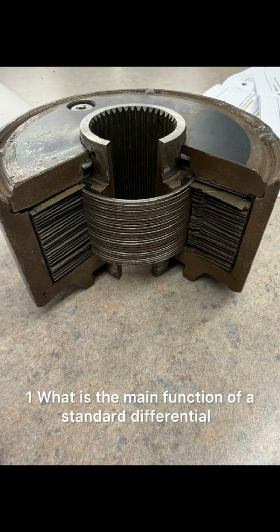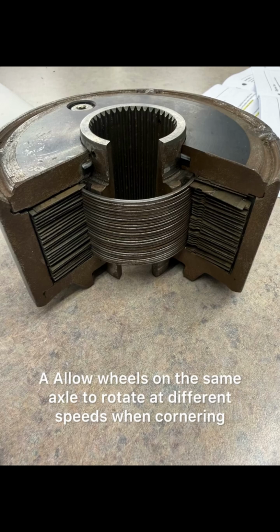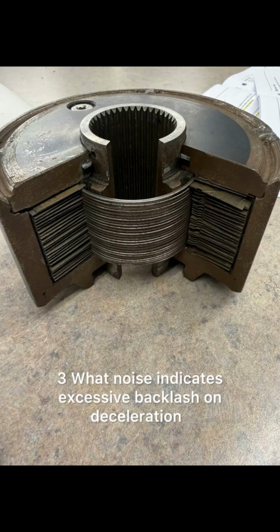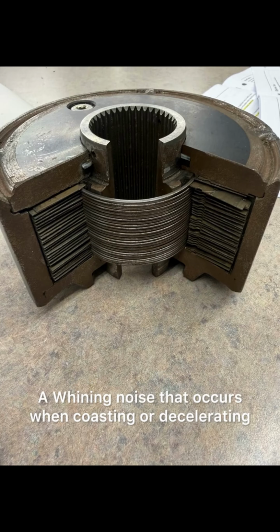1. What is the main function of a standard differential? A. Allow wheels on the same axle to rotate at different speeds when cornering. 2. What noise indicates worn pinion bearings during acceleration? A whining noise that increases with acceleration. 3. What noise indicates excessive backlash on deceleration? A whining noise that occurs when coasting or decelerating.